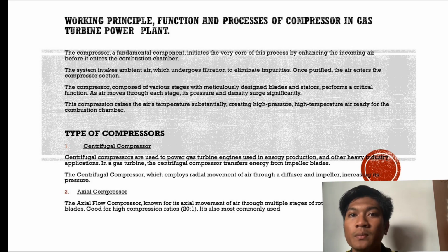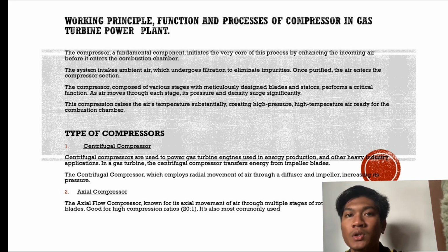Combustion chamber. Firstly, the system intakes ambient air, which undergoes filtration to eliminate impurities and is purified. The air enters the compressor section. The compressor is composed of various stages with meticulously designed blades and stators that perform a critical function.